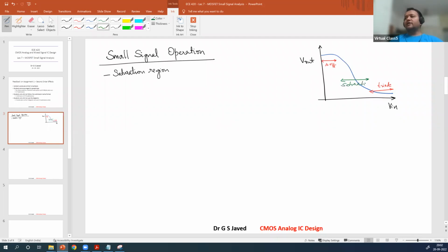In this case, you will define the point where there is maximum gain observed on both points. And that point is what you call your DC operating point, which is going to be operational for most calculations that we will do. This dotted line will define the values V in, V out, which defines the DC operating point for which you operate, voltage in and voltage out. And this is defined here for an NMOS device. It is almost the opposite for the PMOS device.